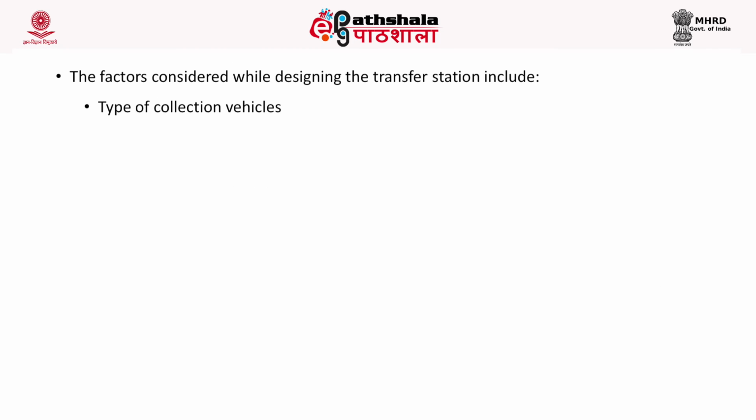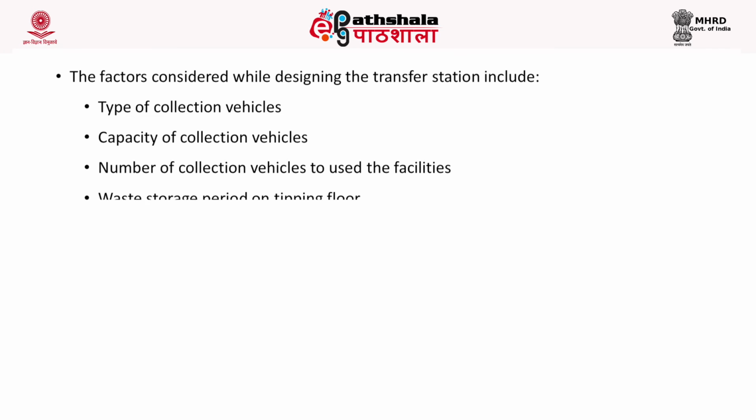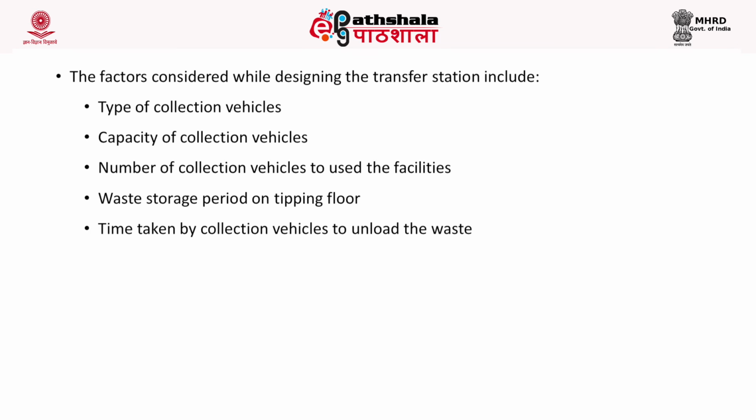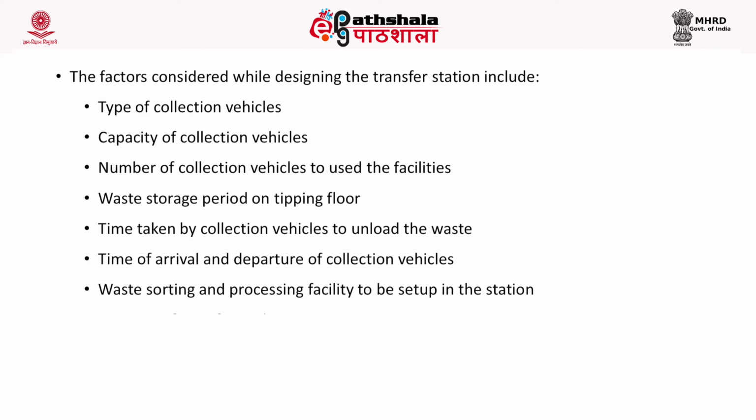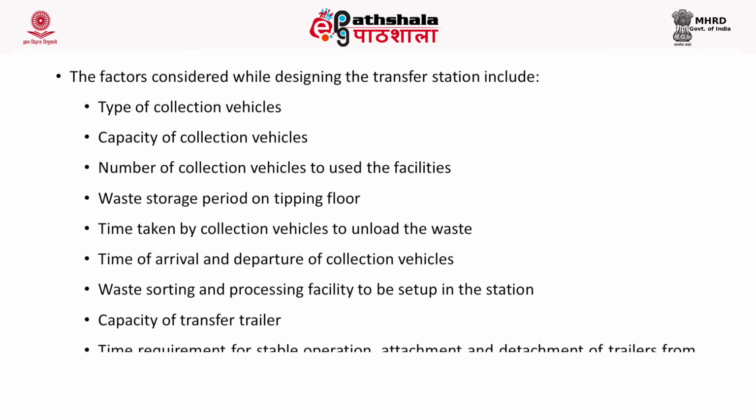Now, the factors considered while designing the transfer station will include the type of collection vehicle, the capacity of collection vehicle, number of collection vehicles that will enter the facility, the waste storage period on the tipping floor, time taken by the collection vehicles to unload the waste, time of arrival and departure of these collection vehicles, the waste sorting and processing facility that is to be set up in the transfer station, the capacity of the transfer trailer, and the time requirement for stable operation, attachment and detachment of trailers from tractors and compactors should be considered.